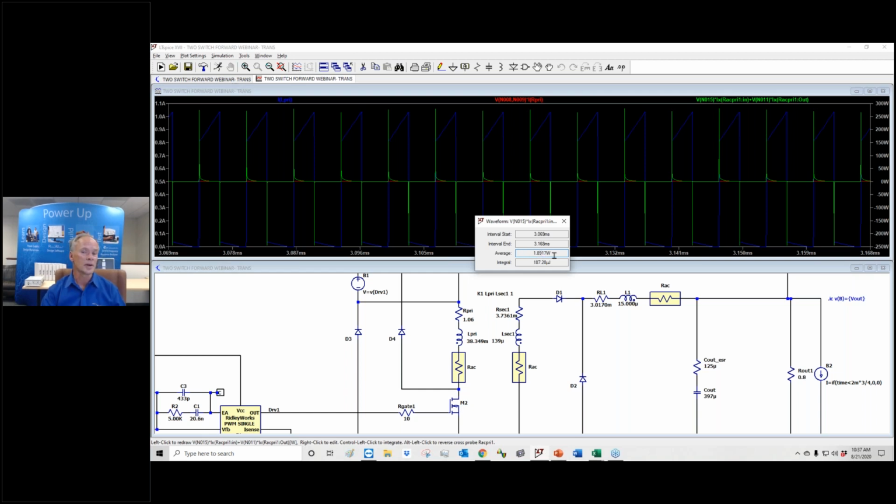Okay. So this is the power of using Spice to do this work for you. Yes, we generated the curve of the AC resistance that came from solving Dowell's equations, or it came from just reading the curves and normalizing those. Then it runs the AC waveform through there and it automatically multiplies in the time domain every harmonic times the resistance at that frequency harmonic.